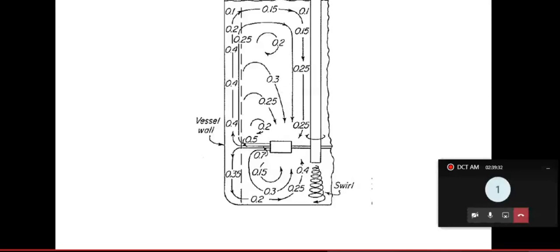So this is the concept of scale-up. Most important thing is what? When we are going from one size to another size to another size to another size, what we are keeping in common is only one thing. Power consumed by the electrical motor per unit volume of the processing material is important. This is the only thing which I am going to pick from first reactor to second reactor to third reactor.